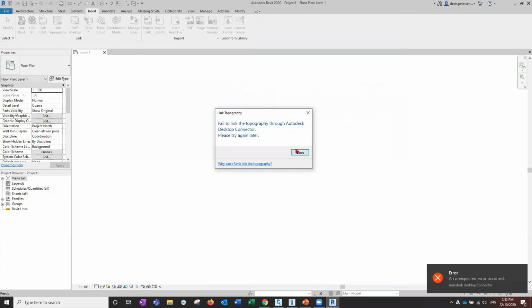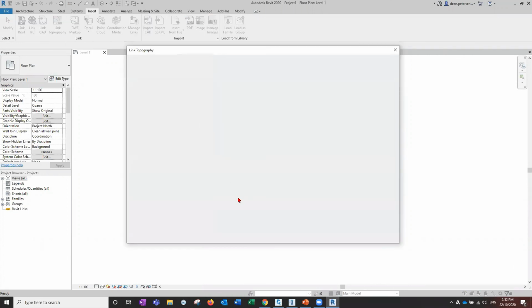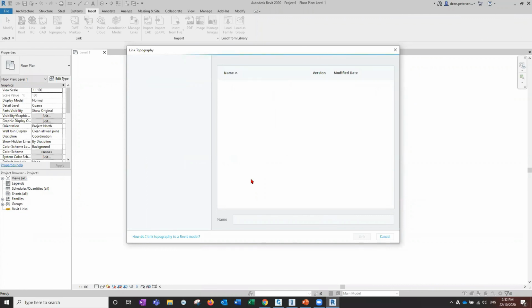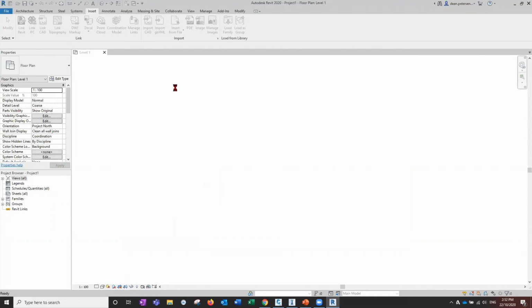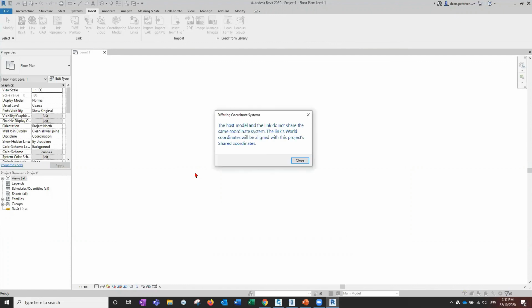I'll link that. Okay, that is because it hasn't finished updating. I have seen that before, so that's okay. We'll use the old one. It does take a few moments to finish writing and get everything through to BIM 360 and update BIM 360. So I'm going to use that one, make a link, and we'll now get that into Revit through BIM 360, and it can be used as an actual Revit topography, and the triangulation is maintained. Now, I haven't set up a coordinate system, so we'll just align it center to center for now.